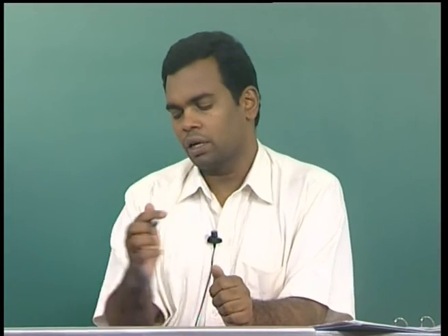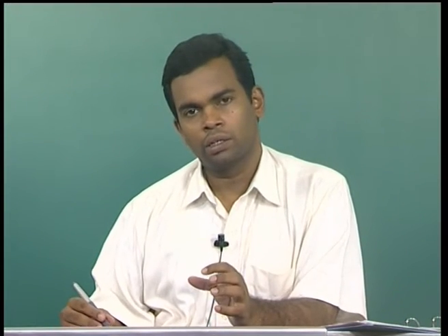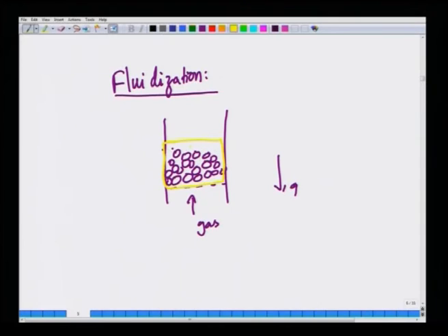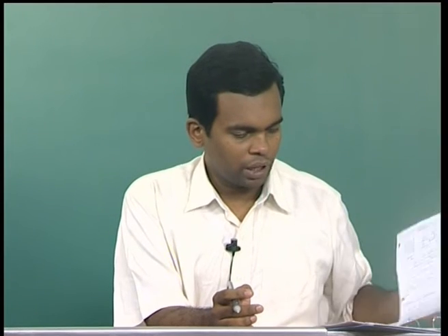Okay. Other design requirements are such that the fluidization should not be such that the particles go out of the bed. Okay. There should not be entrainment of particles outside the bed, because the gas will come in and go out. But when the gas is going out of the bed, it should not take away particles with it. So, we have to worry about those issues as well. So, we will try to address all these issues based on whatever we have done so far. Okay. Now, the idea is very simple.